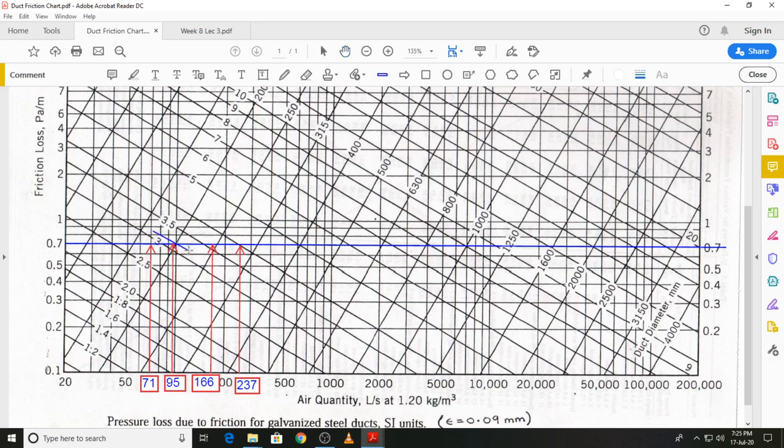You will have a line like this showing the velocity, and this is 3, this is probably 3.25 over here, and if you draw it properly using the right scale, you might be closer to the 3.25 value, but again if you use a value of 3.2, that is acceptable. And now that completes our column for the velocity. The remaining calculation is straightforward.